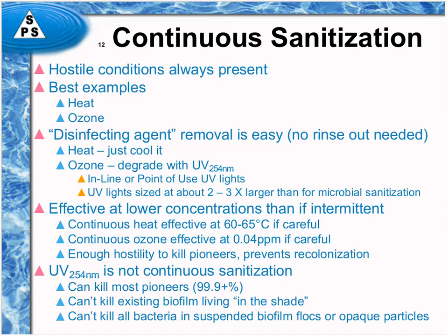And then with the opaque particles, you may have organisms growing in little crevices within the particle, be they a fine from a resin bed or a rouge particle or a carbon fleck or something. It will not be killed on the inside of those because the light's not actually impinging on it.